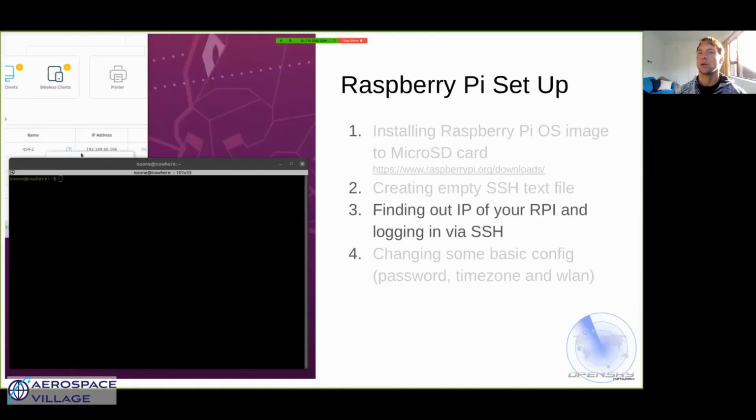After the SD card is finished, we insert it into the Raspberry Pi. Connect the Raspberry Pi to the LAN network using the cable. Add the SDR USB stick with antenna attached to it and power up the Raspberry Pi. Give it a few seconds.